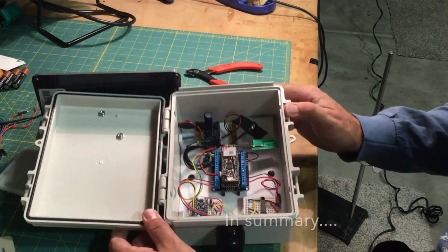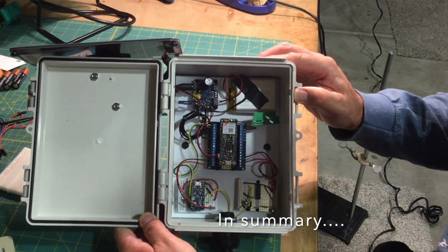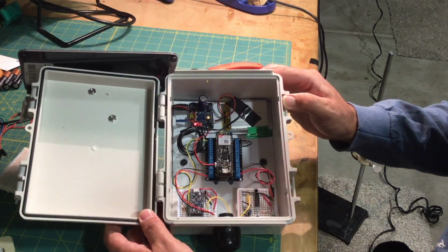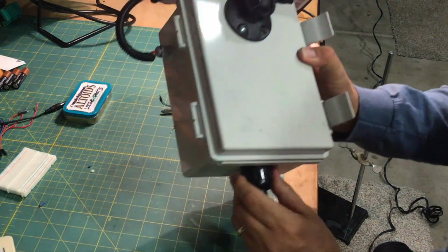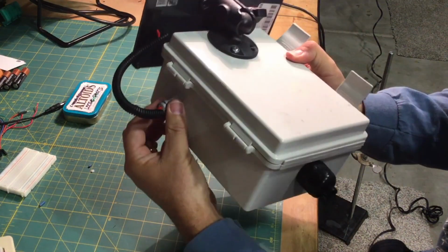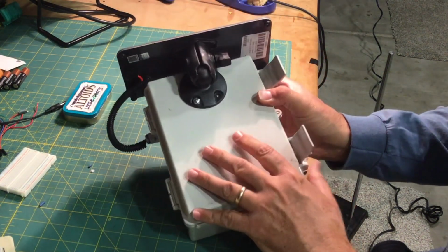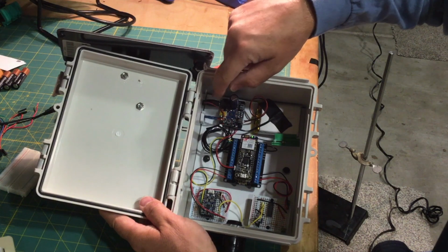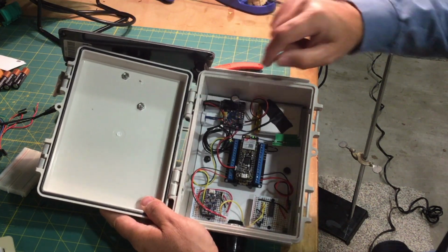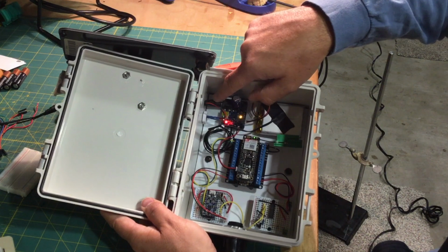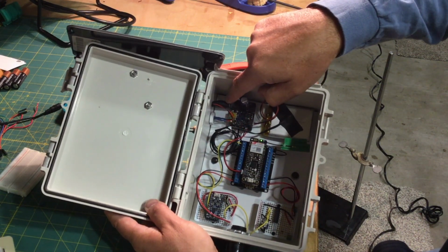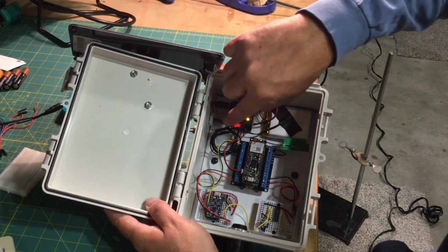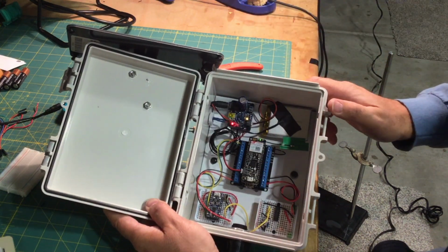Okay folks, so I've gone ahead and mounted that little plastic board with all my tested electronics back inside my box. You can see that I've got my watertight fittings reinstalled. They're nice and tight. This one's nice and tight to keep this from pulling out. I've used that hacked 9-volt connector to power up my solar LiPo charger. It's a little awkward the way it's fitting in here right now, but this is actually good. It's going to keep it from being pulled out, which is the problem that I was having with these wires coming into this little terminal header right there.